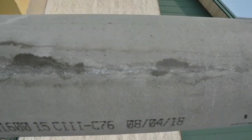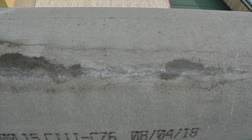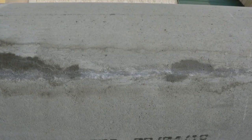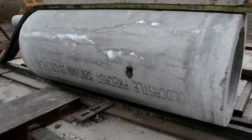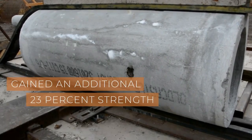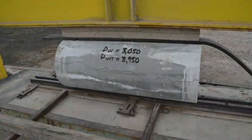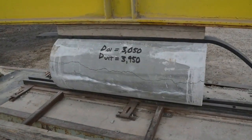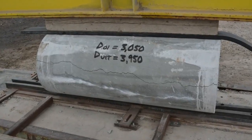The American Concrete Pipe Association demonstrates the principle of autogenous healing in a test that shows calcium carbonate sealing a pipe's minor cracks after 3 days of the pipe being filled with water. Loads were tested, and the cracked but healed pipe had gained an additional 23% strength after 1 month. Our results provide positive anecdotal evidence of autogenous healing's speed and strength, and evidence that minor cracking poses no threat to the soundness of concrete pipes.